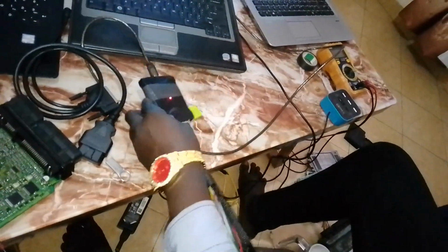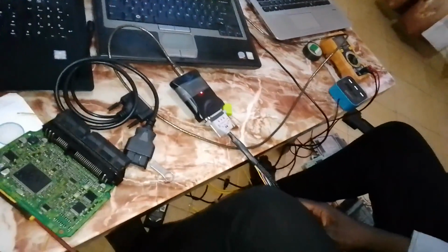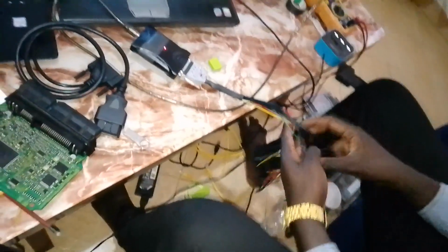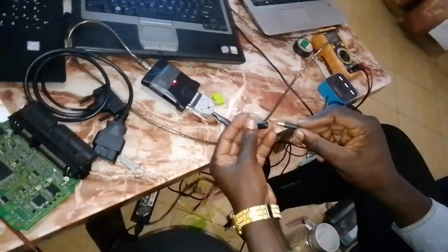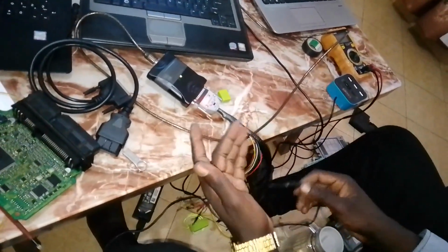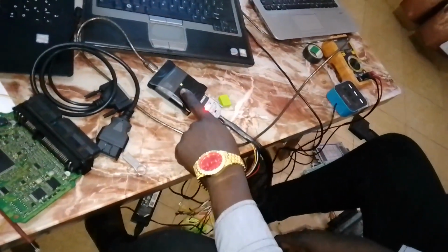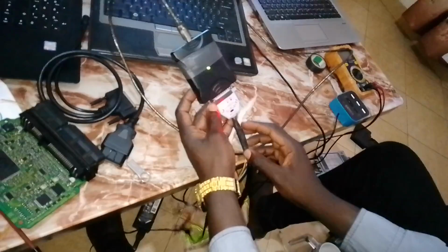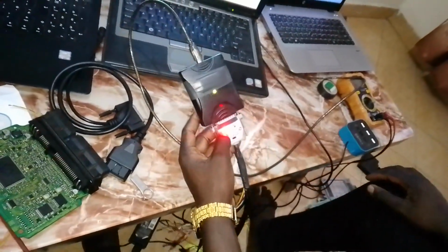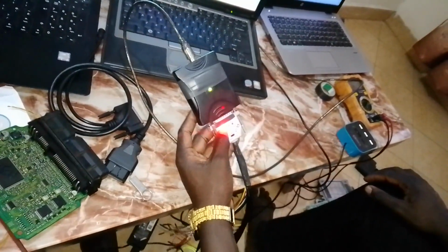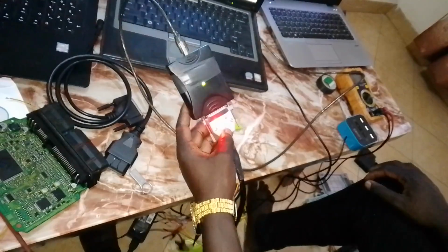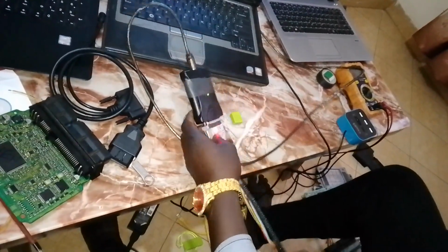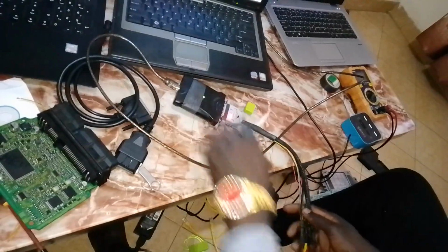So once you've done that, you get your 12 volts adapter. On this there is the power supply connector, so you connect this to this, and when you connect the 12 volts, this light will turn green, and this one works as the ignition switch. So when the ignition is off, only the 12 volt supply battery light will be on, and when you put it on, the plus 12 volts will be live. So once you've connected this one, you can verify.